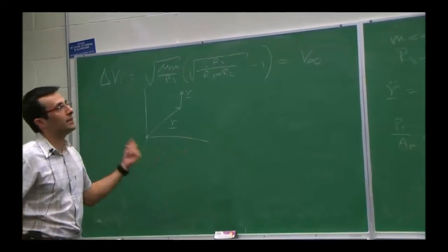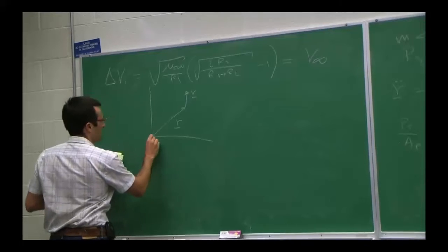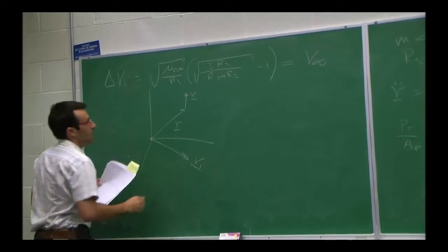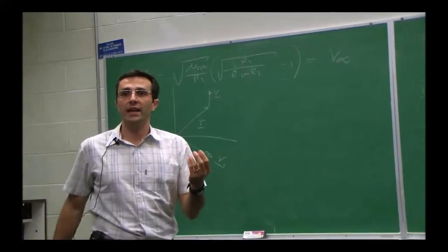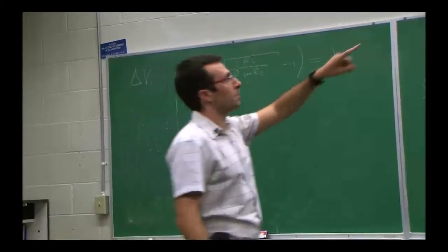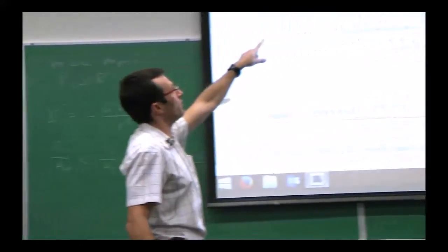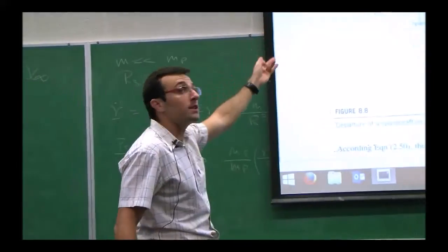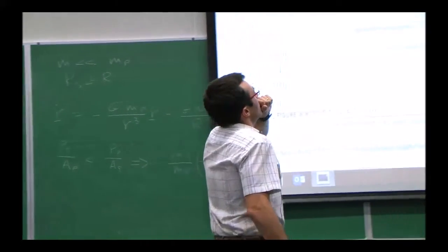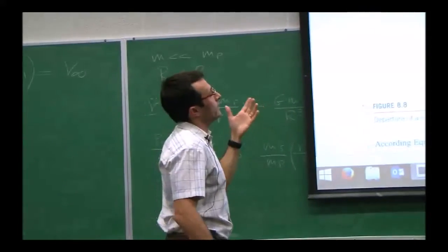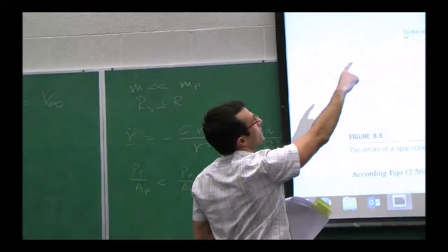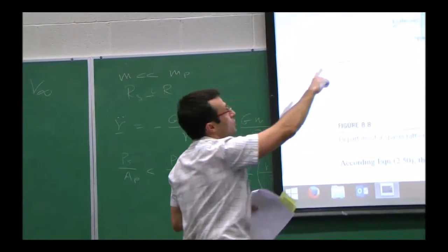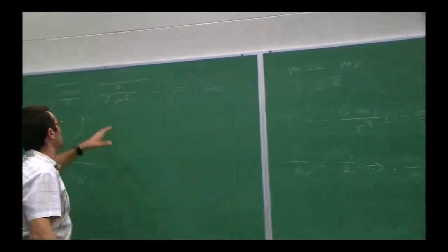So now we have to add that velocity of the planet around the sun, whatever that is, V1, right there, if we want to know how the satellite is moving with respect to the sun. And that's what we define at the edge of the sphere of influence. The moment you reach that imaginary edge of the sphere of influence, you are under the influence of the sun. So what you want to make sure is basically the following, that you go on some kind of hyperbolic path, and you want to make sure that your V infinity is the correct value, so that is giving you this.